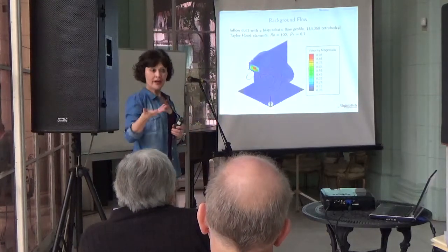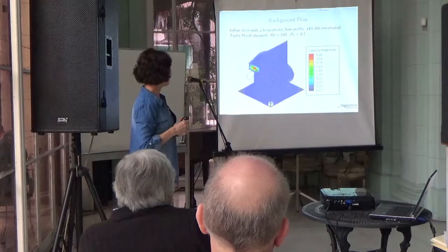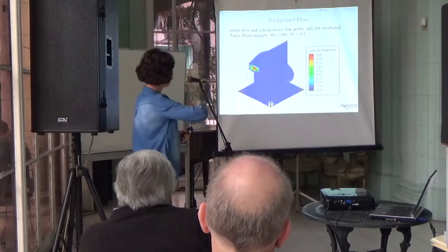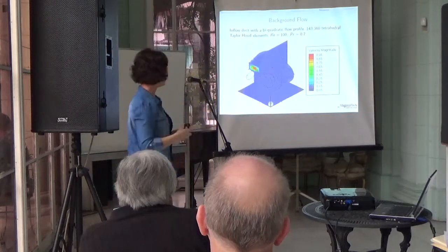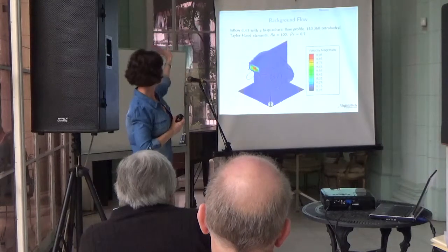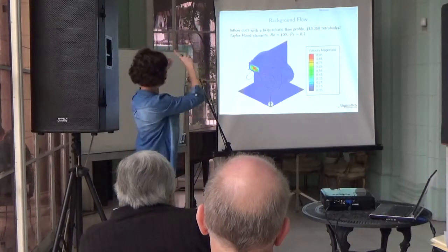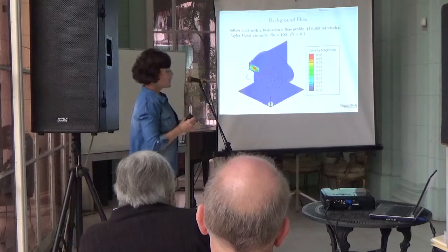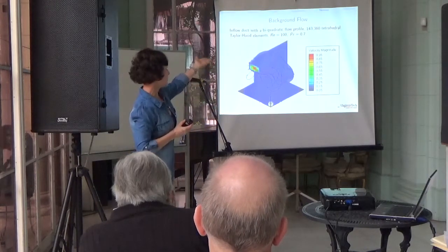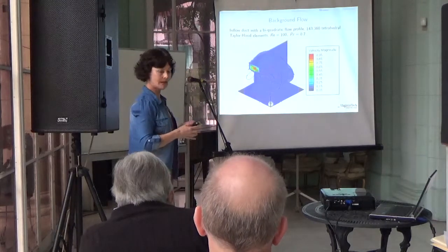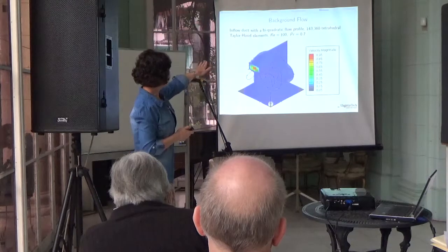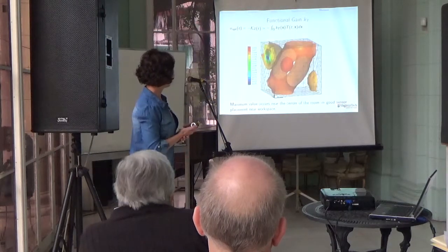So if I were to have full state and I solve the Navier-Stokes equation, this is sort of what the flows look like. You can see if I would trace the particle, you can see what could potentially happen. I have a bi-quadratic inflow profile, so the velocity looks like a parabola. We chose 33 points only in each direction, and that results in 143,000 tetrahedral elements. So just an idea. And the flow is relatively slow, the Reynolds number is 100.